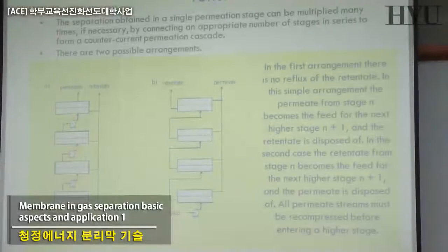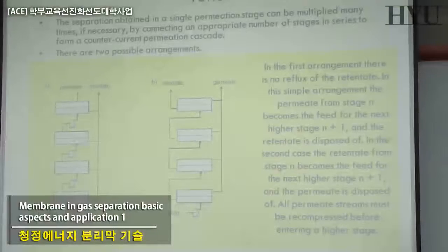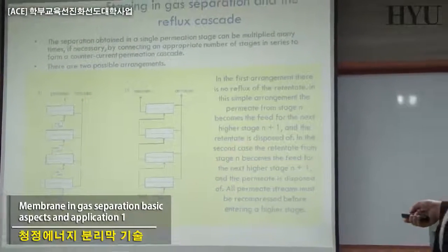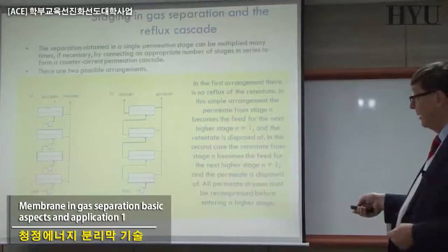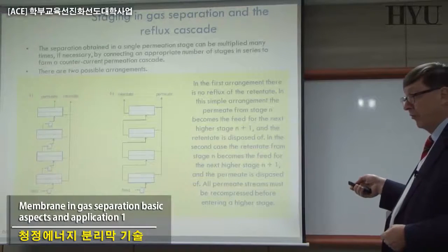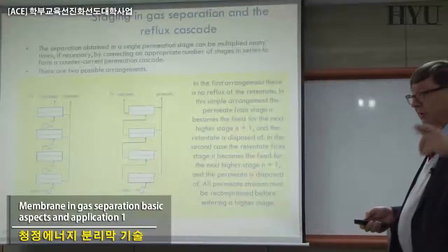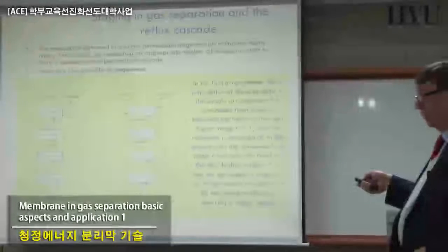The other case is different because here the permeate, or in this case, all the retentate, are mixed together at the end. So at the end of the system, you will have a retentate where we've been mixing the retentate from number one, number two, number three, number four, and the permeate, which is the permeate coming from number one up to number four.